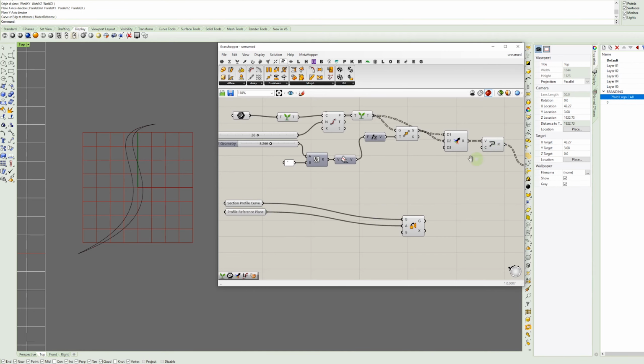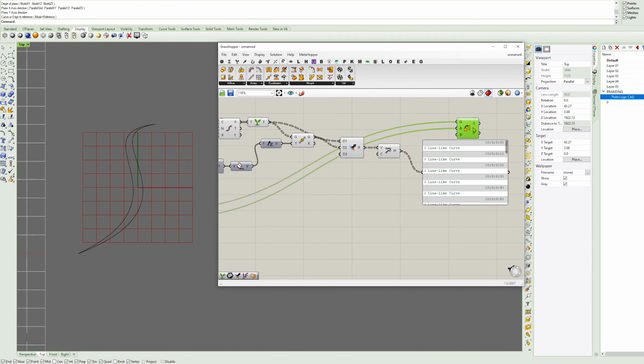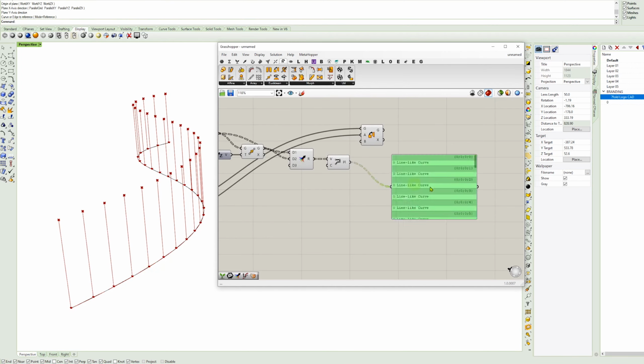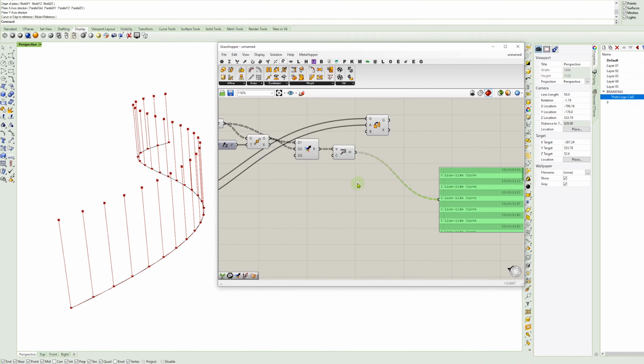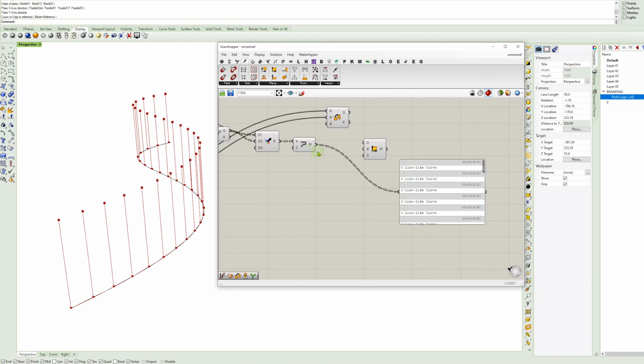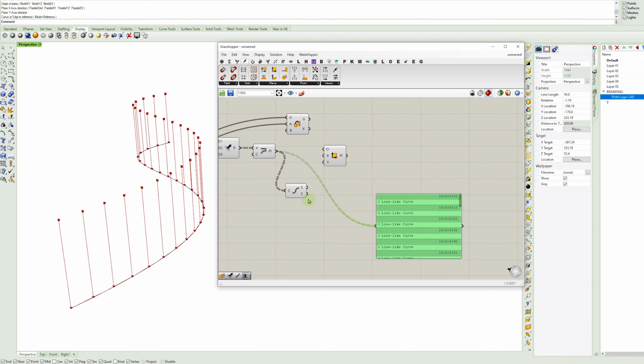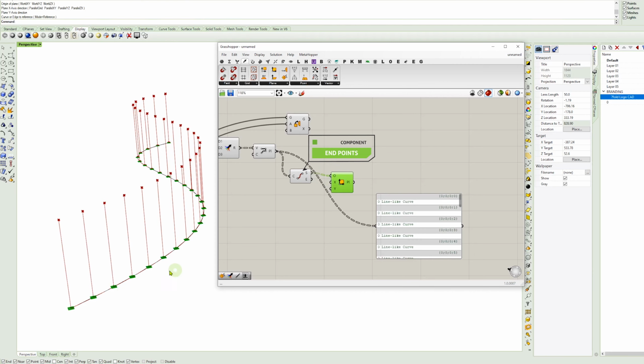And now we need to build our planes on the profiles that we're going to sweep against. So let's go back to our perspective and build our planes. In order to do that, we're going to keep this really easy. We are going to go to the vector tab, construct the plane, and just put it on the point there. Once it's in a line, I could have referenced it from back here, but I prefer to do endpoints right here so that I know if there's multiple vertices, I've always got the start point or endpoint. I'm going to put the start point in as the origin, and that's going to drop some planes in right here.